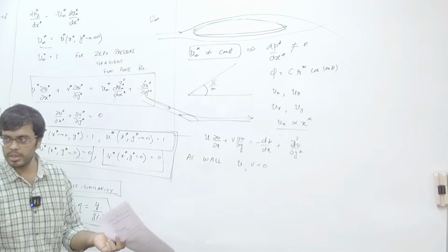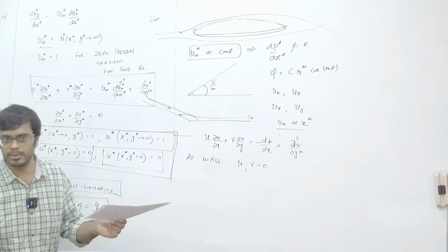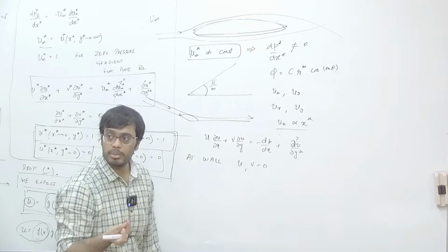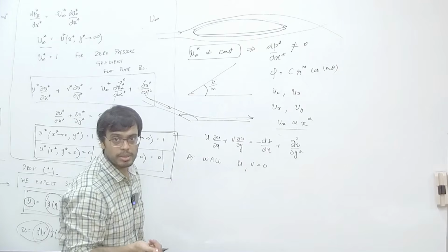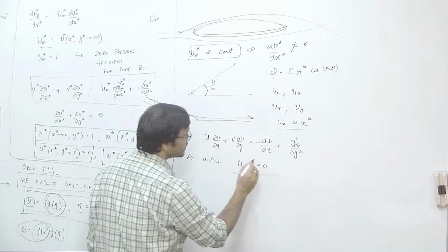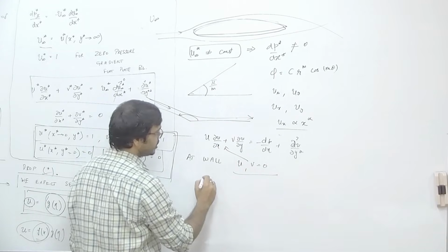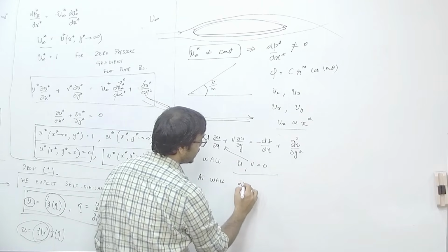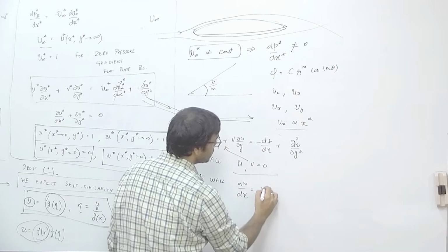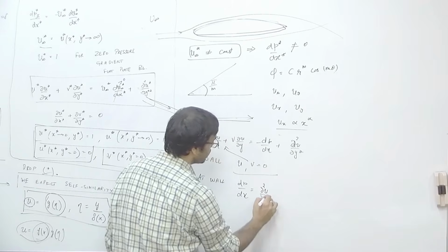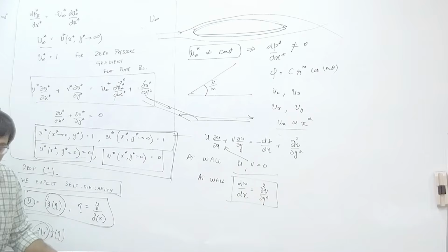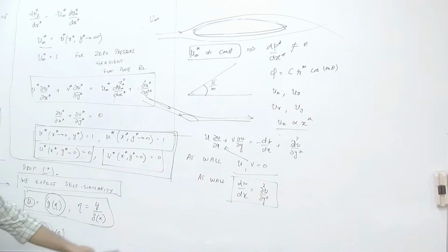These are two orthogonal components, so if they are 0, all components are 0. So, velocity is 0 at the wall, irrespective of the wall being curved or not, due to no slip and hard wall. If you substitute it in the governing equation, you see at the wall dp dx equals del 2 u over del y square.